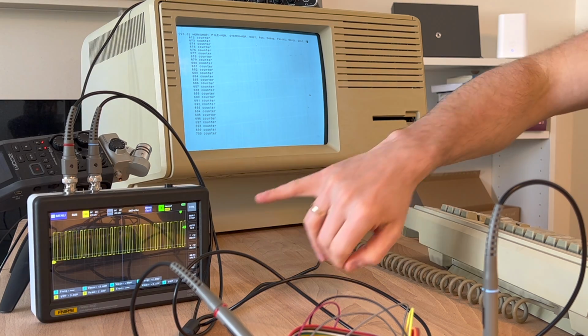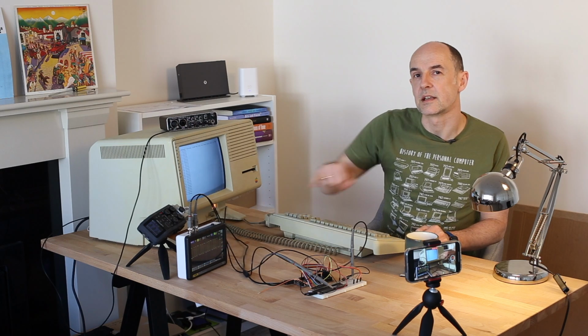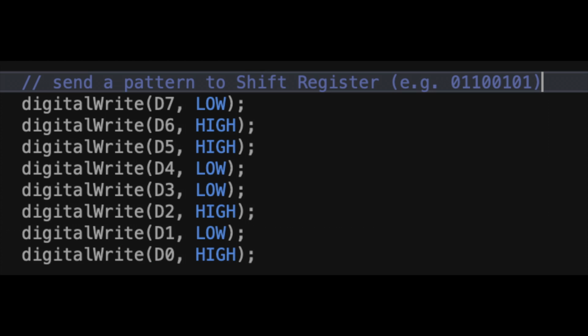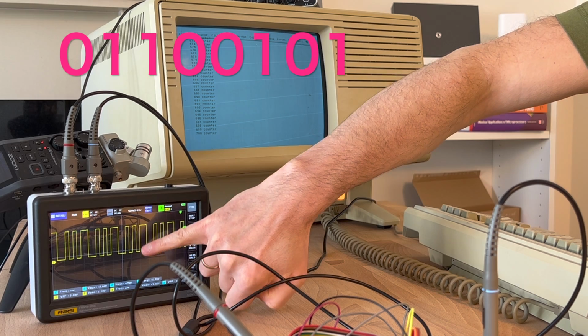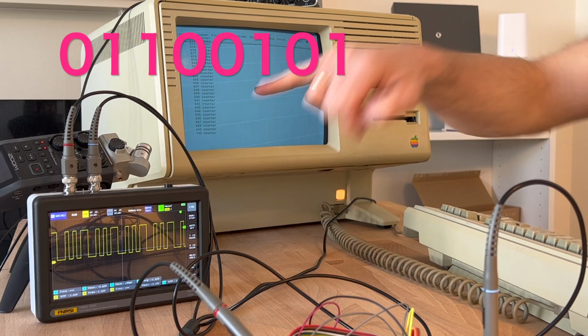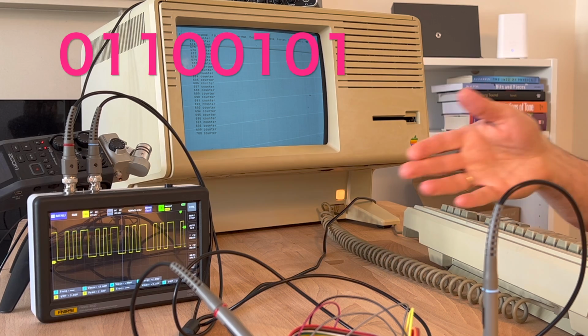It worked. You see the pattern here. When I zoom in, it corresponds exactly to the pattern of ones and zeros which we uploaded to the shift register using the eight parallel data lines. The high states represent ones, so this is a single 1, 0, 1, 0, two ones, two zeros, 1, 0, again and again and again. And the pattern keeps being shifted out. At that time, the CPU is free to do something else, while the 6522 continues to produce sound.